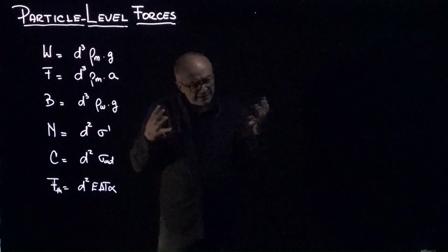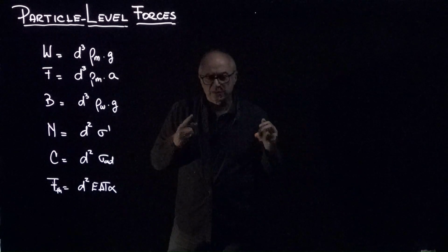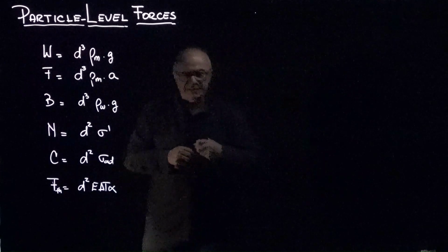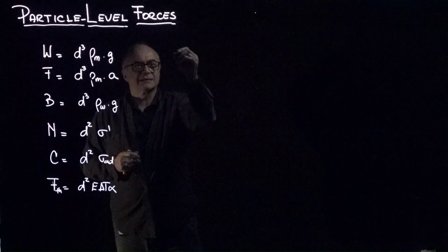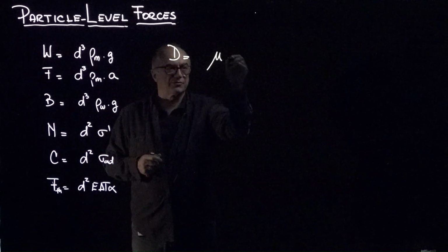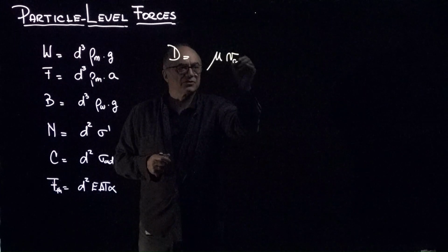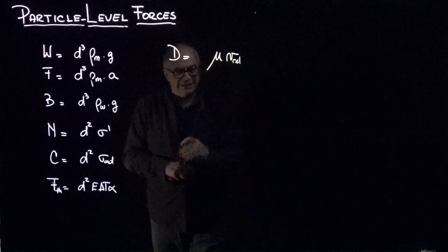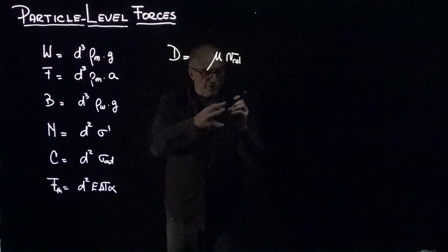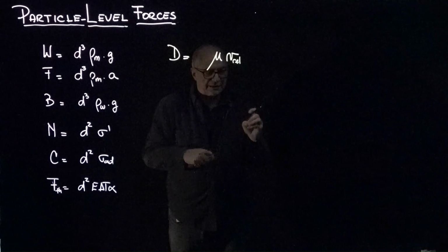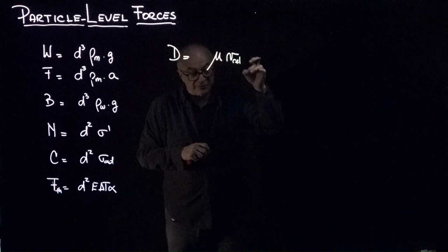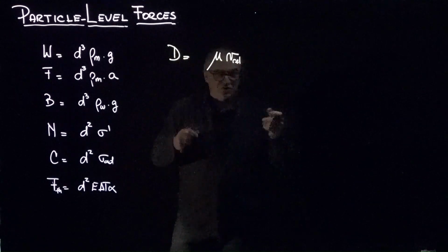This is the type of ideas behind Stokes' law, and what we're looking for now is the drag force that participates in this analysis. So the drag force is going to be proportional to the viscosity of the fluid, to the relative velocity between the particle and the fluid, whether the particle is static and fluid is moving through the pores in soil matter, or a particle is falling through a jar filled with water.